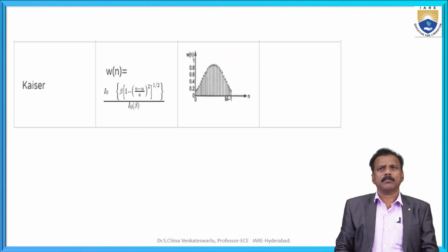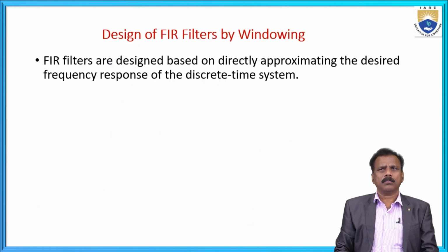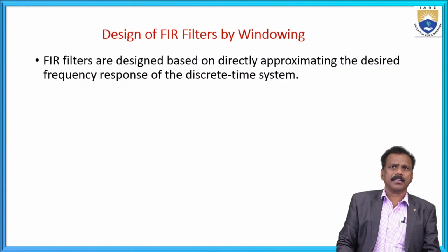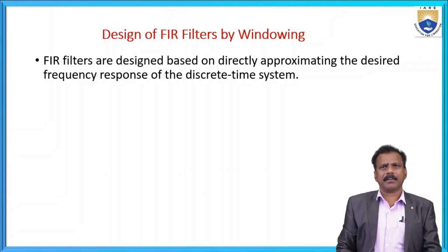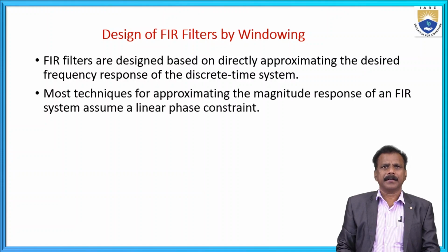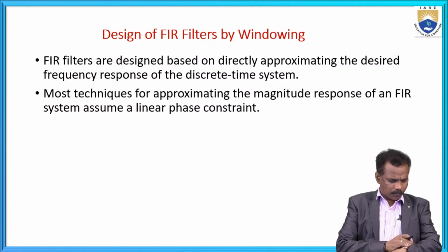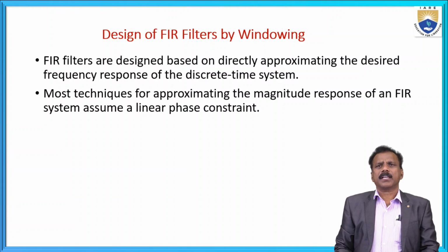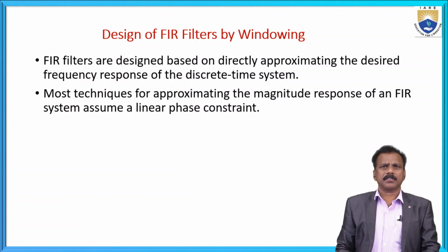Next, the Kaiser window. Now, design of the FIR filter by windowing. FIR filters are designed by directly approximating the desired frequency response of the discrete-time system. Most techniques for approximating the magnitude response of a finite impulse response system assume a linear phase constraint.